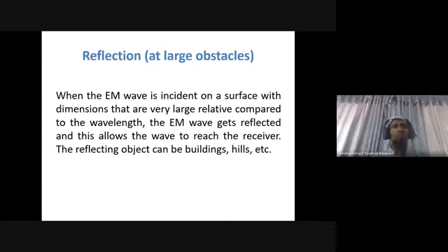Anyway, so reflection. You know what it is, but it can help you get the power, have your signal propagating. Say you are on the other side of a small hill, and the signal cannot penetrate that small hill. So through penetration you don't receive any power, but there may be a large building somewhere which is reflecting the signal, and you get significant power. So you may argue that the power may be very low.